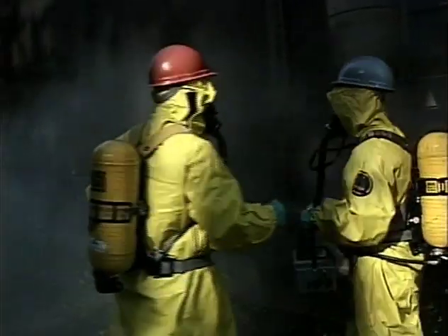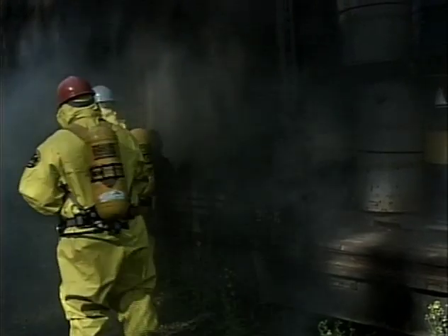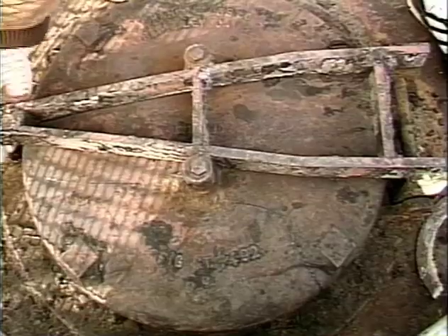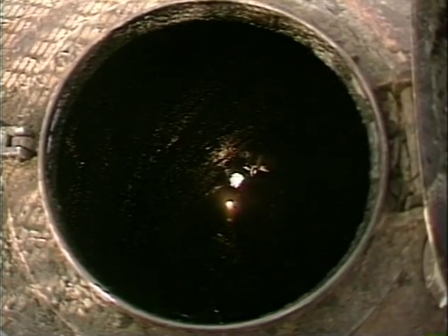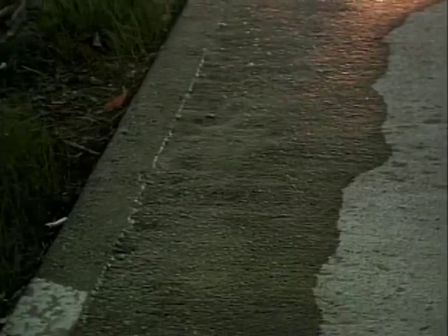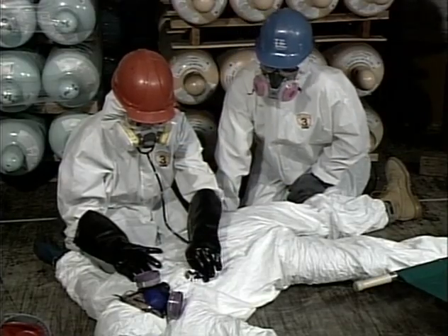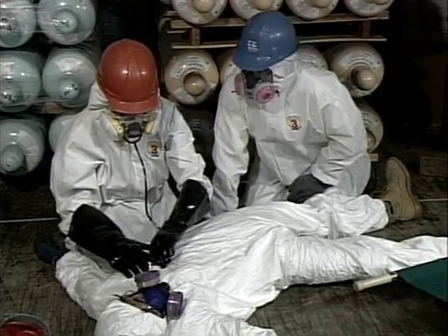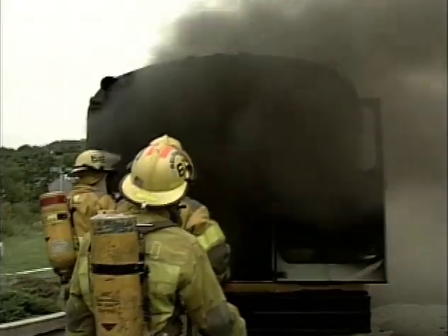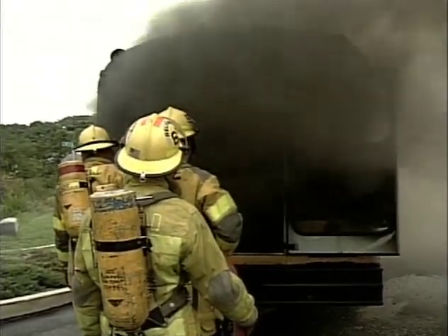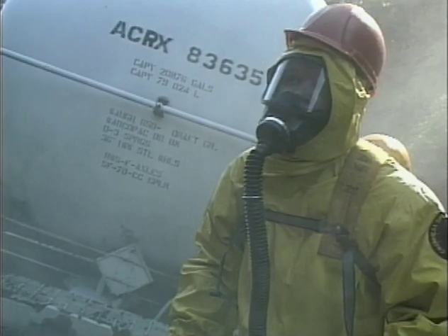The final group of respiratory hazards includes oxygen deficiency and temperature extremes. Oxygen deficiency occurs most often in confined spaces through chemical reactions or fire, or from gases that push breathable oxygen out of the area. A lack of oxygen can cause unconsciousness or even death in a matter of minutes. Temperature extremes can also be dangerous. Hot air can burn your airway, preventing oxygen from being absorbed by your lungs. Severe cold can freeze your respiratory tract and make it impossible to breathe.